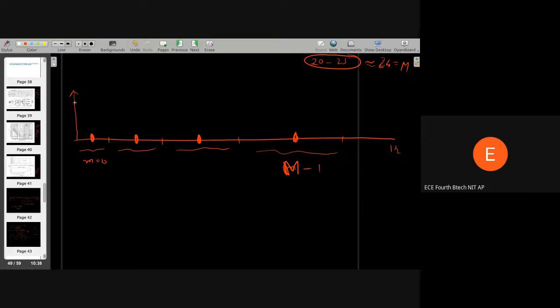So what we do as signal processing engineers is we put a triangular filter, because we have seen, because of masking, that a particular frequency masks the frequencies higher than it and lesser than it, and we have again critical bands. These critical bands, I forgot to mention, are not disjoint, they are overlapping. Because they are overlapping, we choose the bands like this.